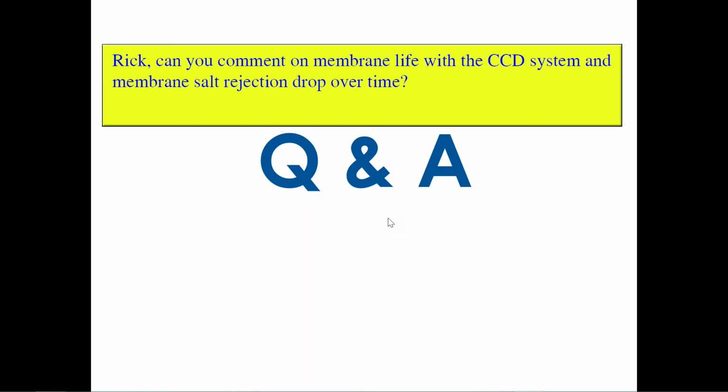In seawater RO, where there's maybe cleaning once a year and maybe less, 6 years is kind of the rule of thumb for seawater applications. And it would be the same in a Desalitech system or in a conventional RO system. And then, yes, as the membranes age and wear out, you expect more salt passage and reduced permeate quality.